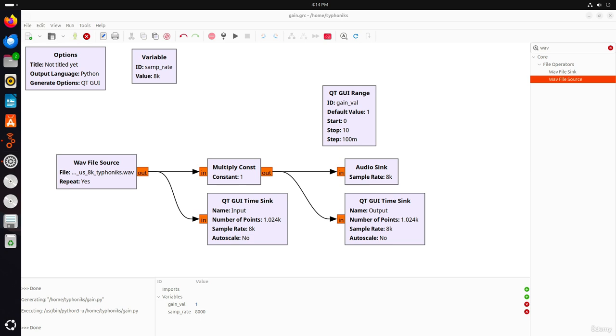Filters rely on the frequency composition of a signal, which can be analyzed using tools like the Fourier transform. Every signal consists of multiple frequencies, and filters selectively amplify or suppress these based on the passband, which are frequencies that the filter allows through, and the stopband, which are frequencies that the filter blocks. In a sense, a filter adjusts the gain or amplification factor of a signal, but this gain varies by frequency. For example, if gain is 1 in the passband, frequencies are preserved, and if gain is 0 in the stopband, frequencies are suppressed.